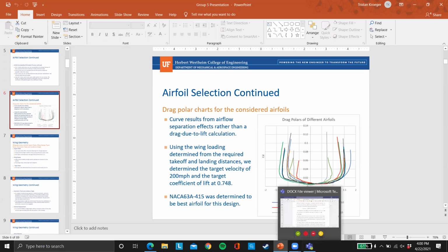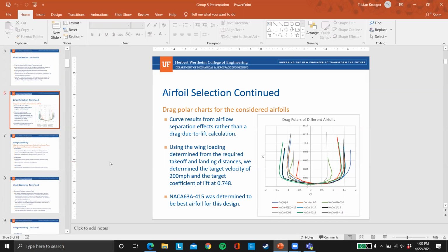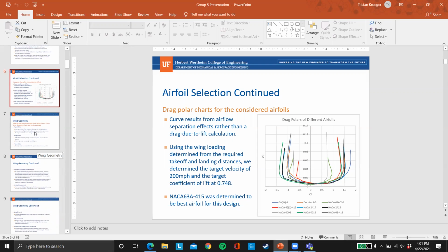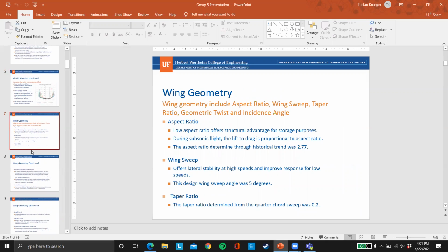For the wing geometry design, there are many items you said are based on the history data. What I want to see is that it's more based on the requirement. So again, we want to put the requirement at the very beginning. What is the lift coefficient required? What is the lift-to-drag ratio required? And then use that as guidance for the wing geometry design, instead of saying this is based on history data, and that one is also based on history data. If everything is designed based on history data, in the end you will design an aircraft that is the average of the history data, right? So at the very beginning, of course, we didn't have anything.